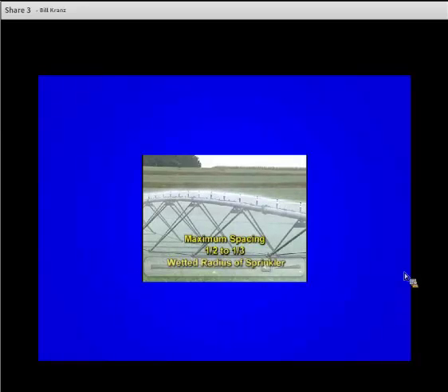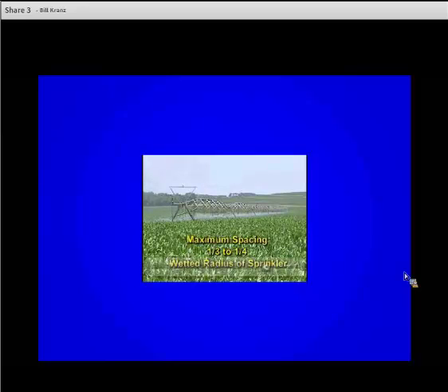So we've got some spacing recommendations here in this particular portion, if we have them on top of the pipeline, and if you have them on drop tubes, or you're down in the crop canopy even closer to the ground than what I'm showing here in this particular image. And again, the idea is to make sure that we get uniform water distribution. And in some cases, we have maintenance issues and sprinkler package issues, where the system is not put in right.